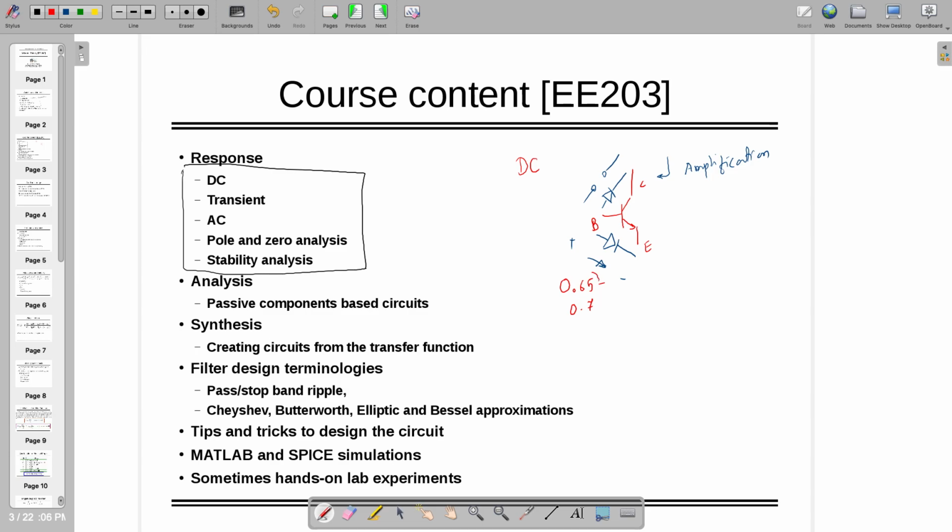But all these numbers which you are seeing right now are DC voltages, not AC. However, AC is also DC at a time. If you have a signal like this and you sample it, you can treat each sample as a DC analysis, DC at a particular time. That's the way all the simulators work.